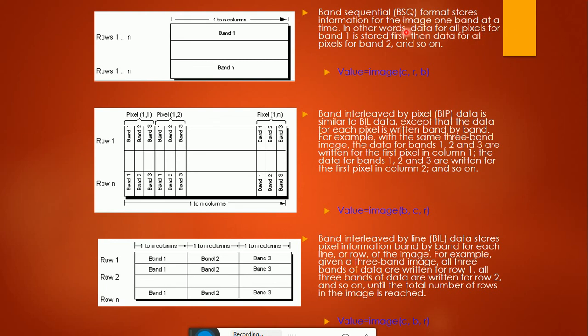Many remote sensing data sets contain high quality accurate data. Unfortunately, sometimes error or noise is introduced in remote sensing data. For example, environmental: atmospheric scattering, cloud; random or systematic malfunction of the remote sensing system, for example an uncalibrated detector creating stripping; or improper processing of the remote sensor data during the actual data analysis, for example inaccurate analog to digital conversion.